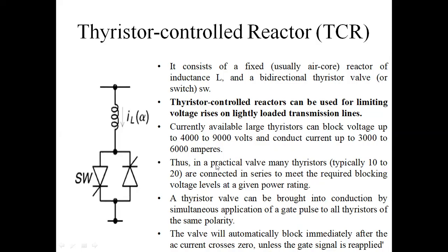Next, in practical values, typically 10 to 20 thyristors are connected in series to meet the required blocking voltage levels at a given power rating.